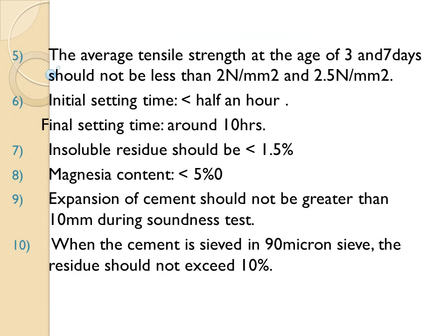The average tensile strength at the age of 3 and 7 days should not be less than 2 Newton per millimeter square and 2.5 Newton per millimeter square respectively. Initial setting time should be less than half an hour. Final setting time around 10 hours.